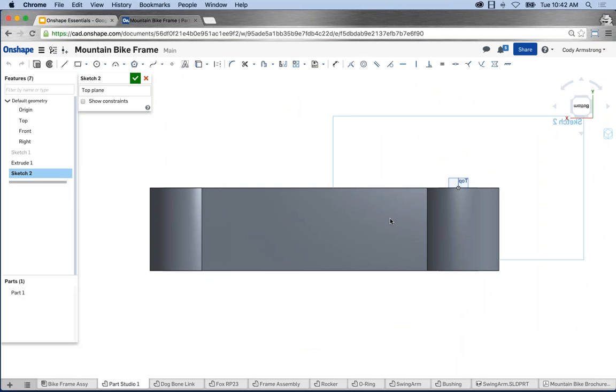So now what I'd like to do here is just draw a few simple lines. Again, I'm going to use those references to attach horizontal constraints to the origin. And then I'd like to add just a few dimensions. So add a dimension here of 9. For an angle dimension, I don't have to do anything special, just select the two lines. It defaults to angle. Now what I'd like to do is take the geometry I have so far, just these 3 lines, and offset all of them to create a closed loop.